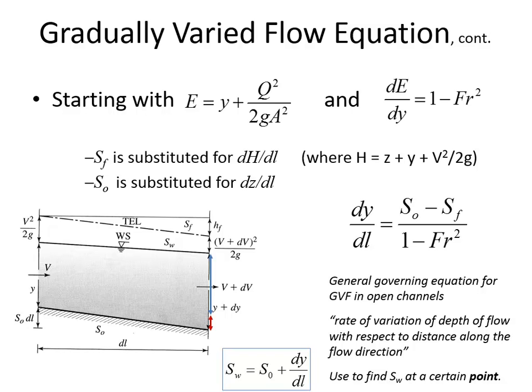But actually now that I think about it, we have to be careful with the signs because this is positive, but we sometimes just by convention don't bother writing the negative sign in front of a channel slope that's downhill. So actually we'd need to put the negative sign there because that's downhill and this is getting deeper in the direction of flow. So I'd need to find the difference between the two to find the water surface slope with respect to horizontal. Yeah. Because the 0.00015 is downhill.